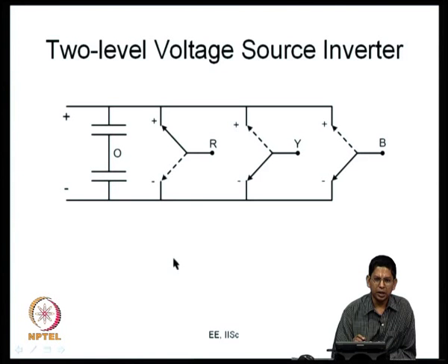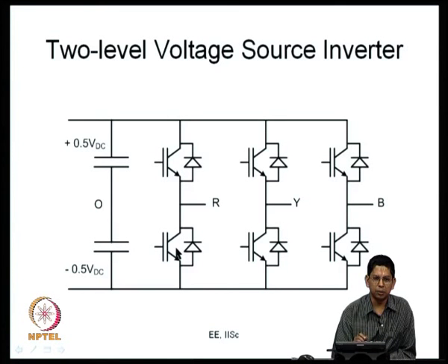And so, we have been looking at how to modulate inverters at low frequencies. That is what we have been looking at over the last couple of lectures. One of the methods that we have come upon now is selective harmonic elimination. Here I have indicated IGBT inverters; as I mentioned, this could be any kind, but at very high power levels it could certainly be high voltage and high power IGBTs.